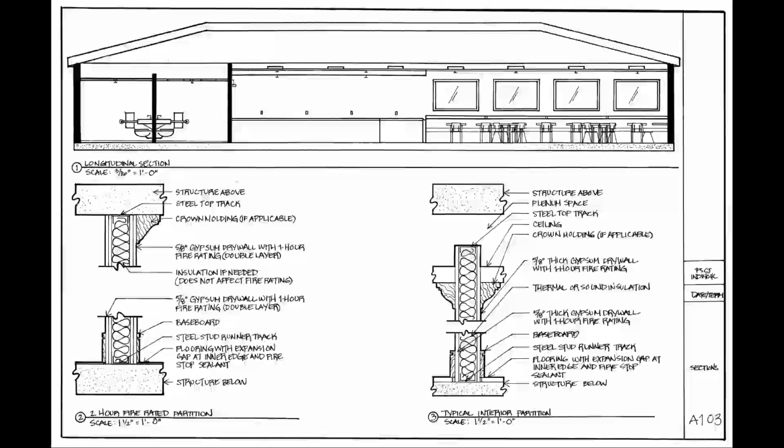We see all the spaces through the walls, beyond the walls, and up into the ceiling and down into the floor. So the difference between an elevation and a section is that an elevation shows finished walls that could be perceived by a viewer standing inside. A section shows the same things as an elevation with additional information about the structure.